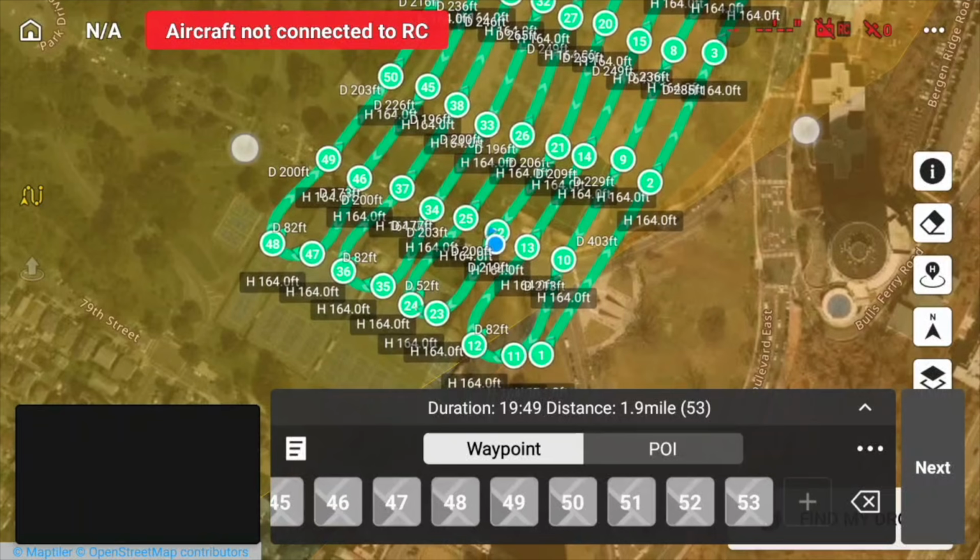The most important thing to remember is to extend your flight path beyond the site boundaries and create 2 waypoints at each loop. You should also have 2 waypoints positioned right at the edge of the area you're mapping. This setup gives you greater flexibility when adjusting and straightening your lines, helping you keep all flight paths tight, parallel, and evenly spaced for a clean and precise 2D mapping layout.